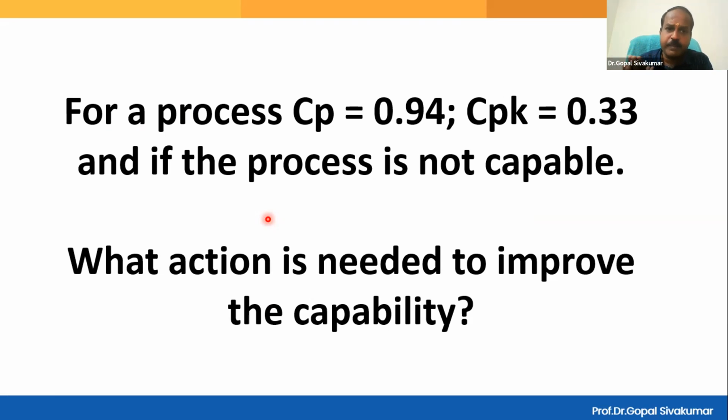Is your average okay? Is your variation okay? Are you happy with the Cp? What is the industry standard? No, both are in trouble. Both Cp and Cpk are under deep trouble. We need minimum 1.33 for non-critical process, 1.67 for critical process.